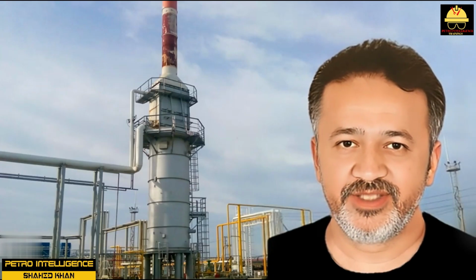Direct-fired furnaces consist essentially of a battery of pipes or tubes that contain the process fluid and pass through a firebox. These tubes run along the inside walls and roof of a furnace. The heat released by the burners is transferred through the tubes and into the process fluid. The fluid remains in the furnace just long enough to reach operating conditions before exiting and being shipped to the downstream processing unit.